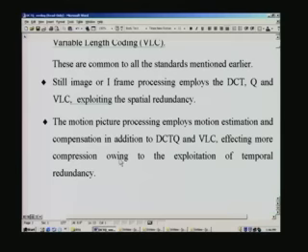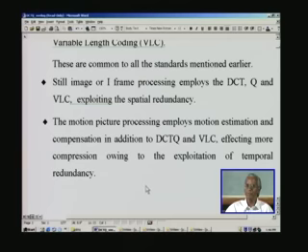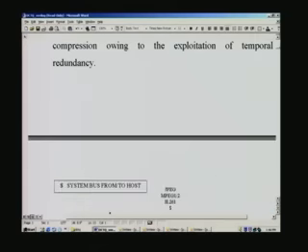And herein we expect much more compression than is possible here, in the sense that we need to code only where there is some motion. For example, you are looking right at the image here, and there is practically no change in motion. So there is no point in coding the same thing again and again frame after frame. Even if you see the speaker, you will see only the lip movements or head movement, eye movements and so on. So what is the need for coding the rest of the picture? That is precisely the background here, and thereby you achieve much more compression there.